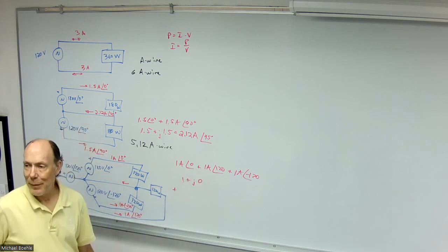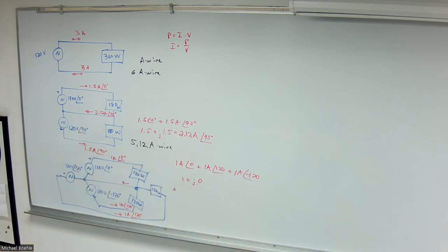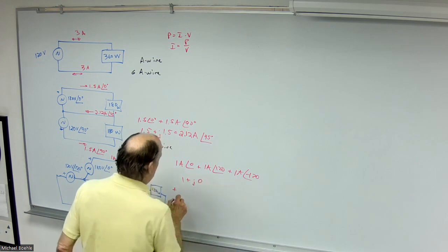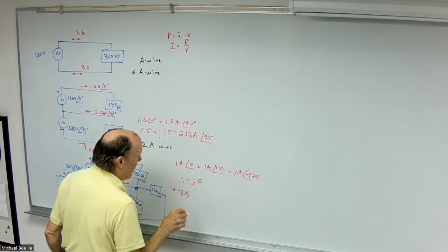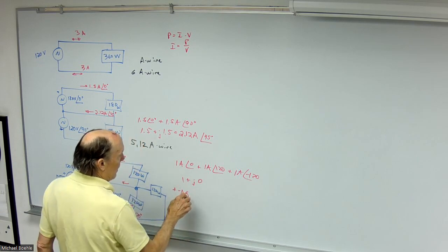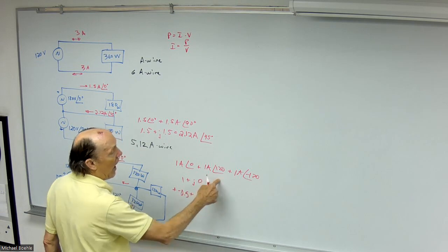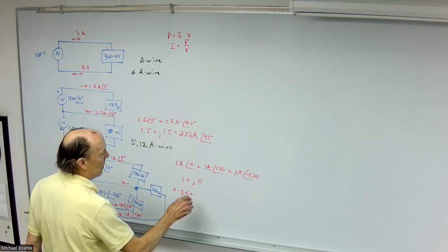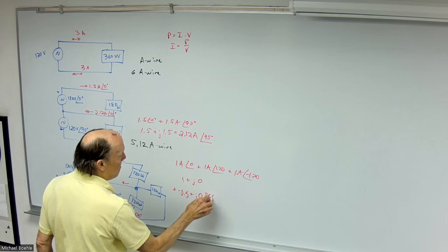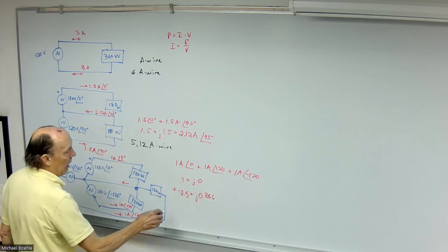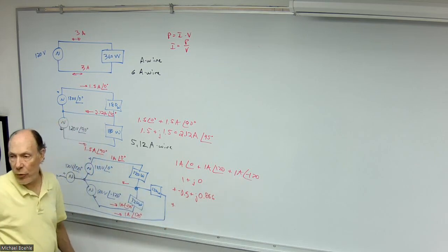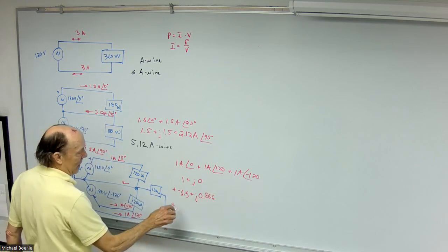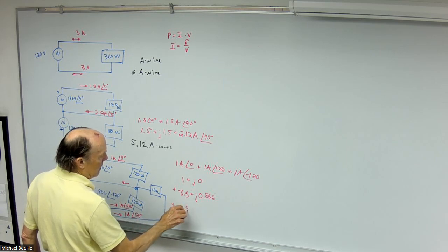What does that end up being? So we're going to take 1 times the cosine of 120 degrees. Negative 0.5. Okay. So this one will be minus 0.5. And the sine of 120, 0.866. Okay. It goes longer, but that's just a good round. And then this one, negative 120 degrees. That's positive 0.5 and a negative j0.866.